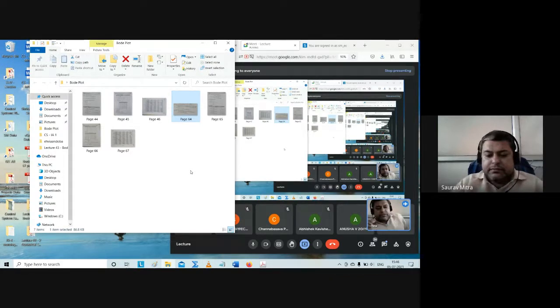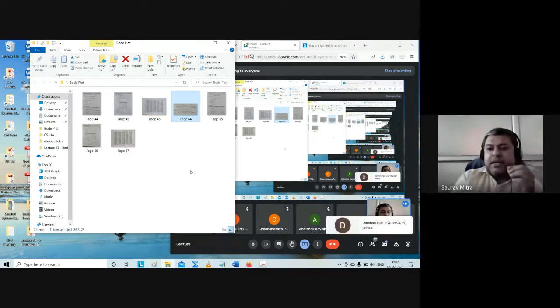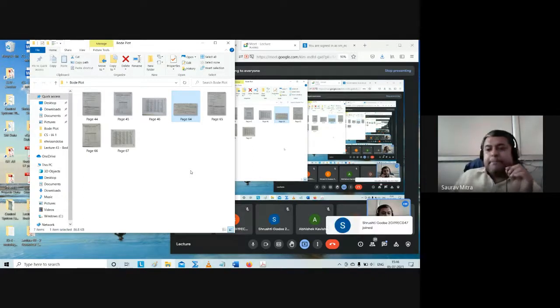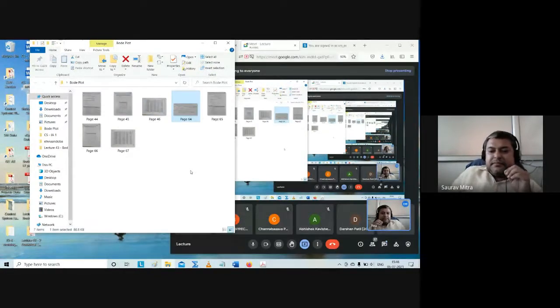So if we take the value of k as 3.16, in that case we are going to get a gain margin of plus 10, instead of plus 20. Can anybody tell me what is better, a gain margin of plus 20 or a gain margin of plus 10? Can anybody answer? Is a bigger gain margin better, or a smaller gain margin? Is gain margin plus infinity good, or gain margin plus 10 good? The answer is, the bigger the gain margin, the better.